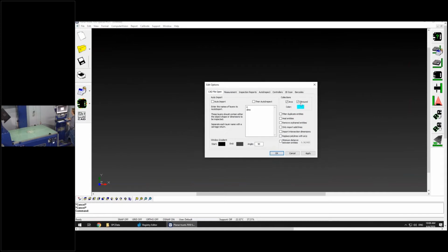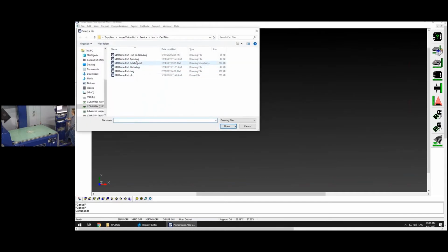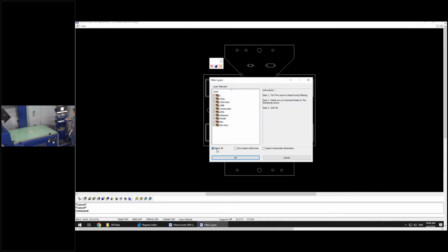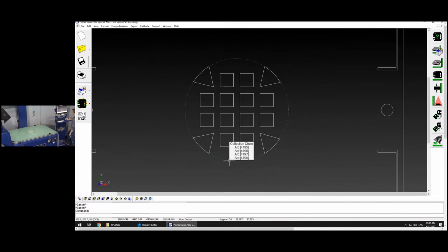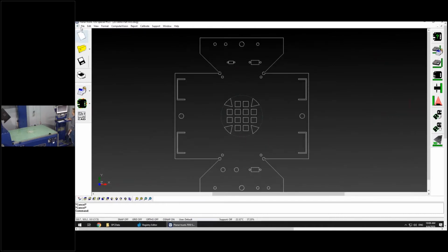And then the same thing for those that use collection arcs. I have a program set up here to show off the arcs. Again, leave it selected, because worst case, maybe you want to grab this nominal where all these arcs have the same center location, so it created one diameter for you. I could grab the location of the center part. I could grab the diameter. I could also grab true position off this collection circle. All that is now useful that I can program into my CAD model.